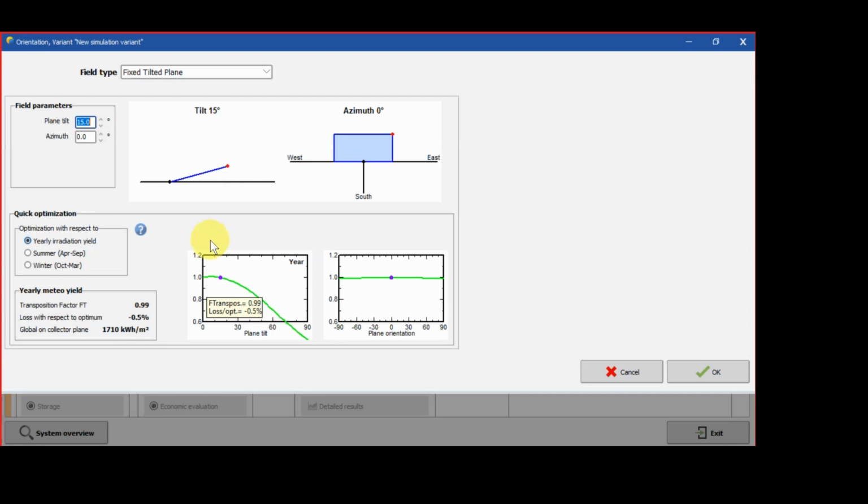But sometimes in your design, you may not have the benefit of setting your own azimuth angle. Sometimes you want to install on a rooftop, and the rooftop already has specific angles you need to follow. So for example, now let me put the azimuth angle at 45 degrees. So this is the position of your module now, pointed towards the south, 45 degrees, tilted 15.